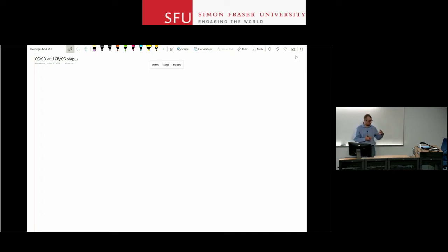They are called, for PNP or NPN transistors, common collector or common base stages. And the MOSFET equivalents are, of course, common drain and common gate stages. Very similar to each other when you use a MOSFET or BJT. We are going to analyze the BJT case first, but I'll show you the MOSFET equivalent and the formulas for the MOSFET equivalent at the second stage.